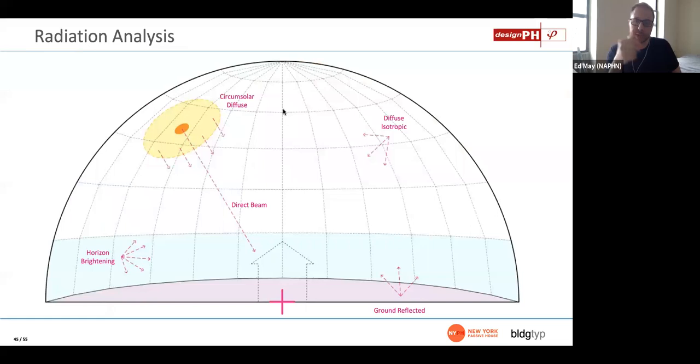What this simulation is actually doing in the background is simulating radiation incident on the window. The way it calculates those shading factors, remember, is by first figuring out how much radiation would be incident on the window with no shading. So it eliminates all the shading from the scene and calculates radiation. Then it brings the shading back into the scene and calculates the radiation as a result with that shading in the scene. And then one divided by the other is going to be your shading factor.